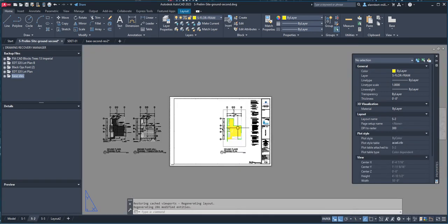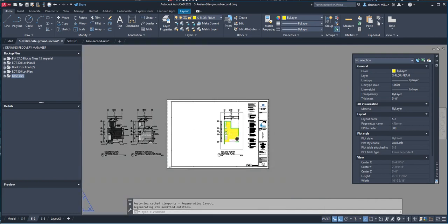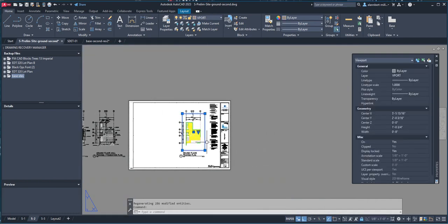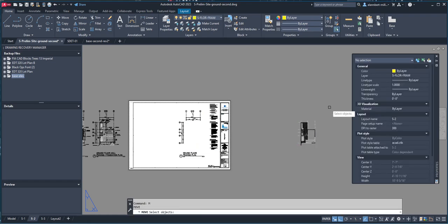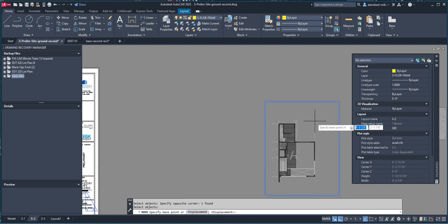So how do we now go to the view of the roof framing? We click on the viewport, and we glide that on the side here until you see this. Okay. Once you have that, then you push back the other corner of the viewport, and then you simply bring this viewport by moving the viewport and holding it on one of the grids here. Okay, so Control F3.